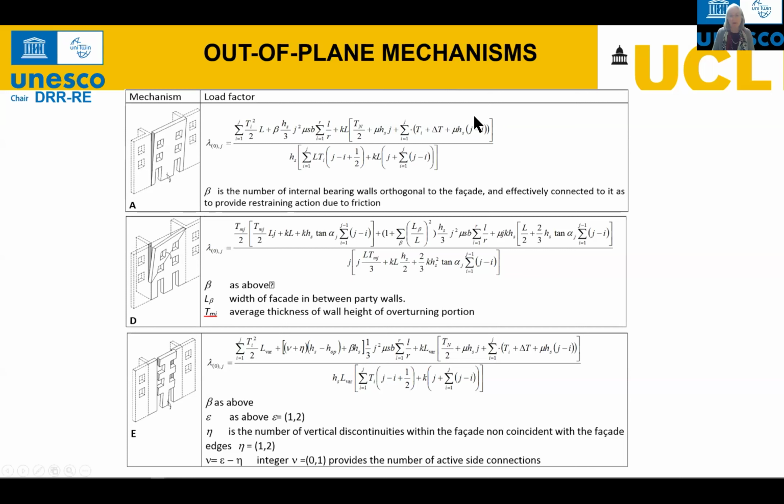And these are the loads that are transferred to the facade with the walls, with the floors and stories. So the relationship here between the restoring moment and the overturning moment will give us the eventual collapse load factor. This one is slightly modified if we consider only half of the facade, because a crack will occur diagonally instead of vertically.